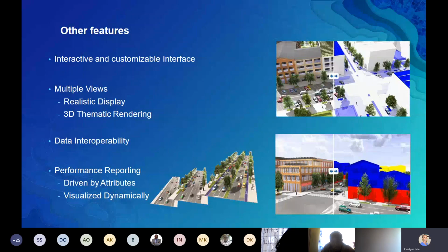We can now import data sets from various formats. You can import data sets if you're working with feature classes. You can import feature templates to ArcGIS CityEngine. If you have your data in a file geodatabase, which is actually easier since you have all your data sets in one place, you can import that to ArcGIS CityEngine.